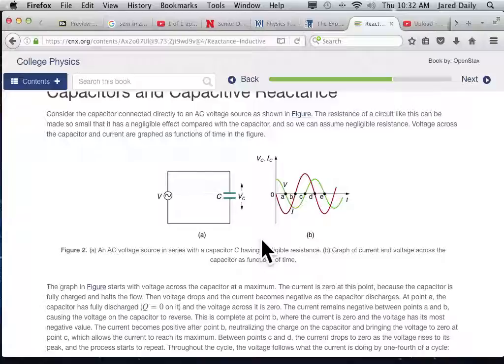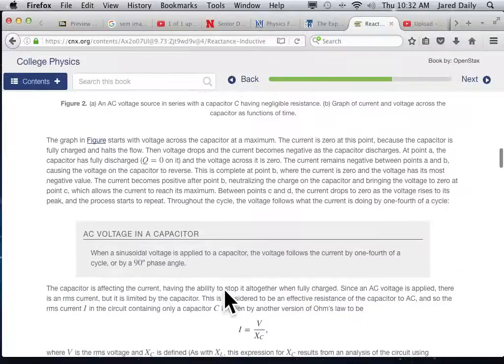What an inductor does is it stores energy in a magnetic field, but it lags behind the voltage. A capacitor sees that voltage right away, and it allows current to flow to it right away because the capacitor is empty, right? But eventually the capacitor gets full, and it doesn't allow any current to flow anymore, right? So it behaves just the opposite of an inductor. So it has just the opposite effect. For example, instead of allowing low frequencies to pass, capacitors will allow high frequencies to pass. And so we can actually start to choke things off with this.